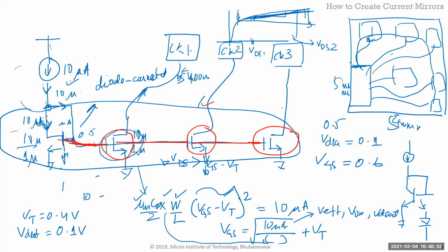And these are short ones because they're just in the same IP. Now I have some big clock signal going close by, and like I always say, everything is a capacitor in IC. They couple and they put a lot of junk noise here, right? That noise is this VGS noise here, squared. The ID is going to be a huge current. So your noise is going to get coupled. You're going to have huge noise on your ID. Okay.